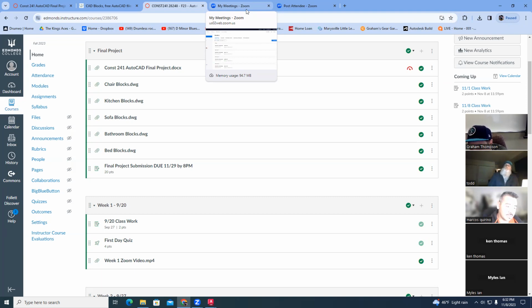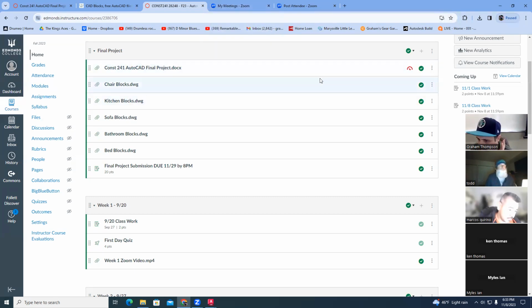Now, sometimes you might not necessarily see it in plan view, only because the architect is trying to portray that there's a stove underneath it, and it's kind of hard to see through that. But you could also stack them and show the border of that range hood and then the stove underneath it. It's what's called a wireframe view instead of a hidden line.